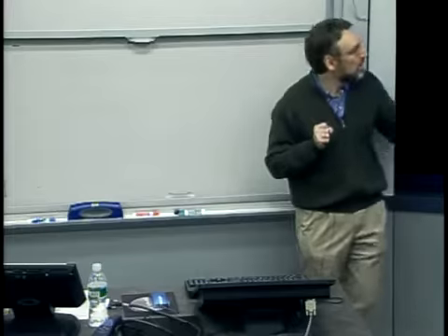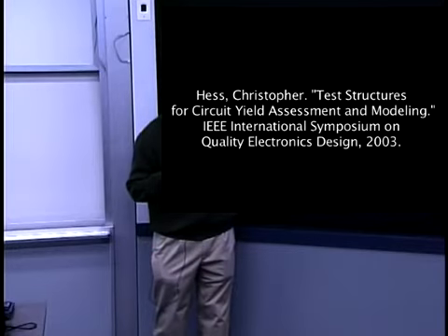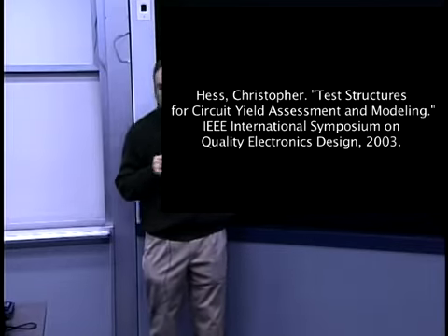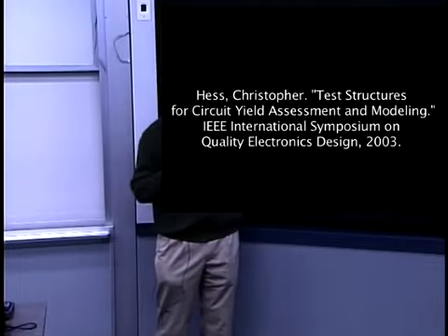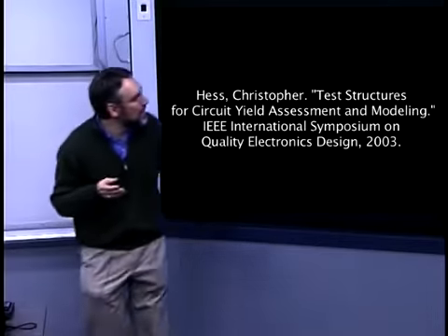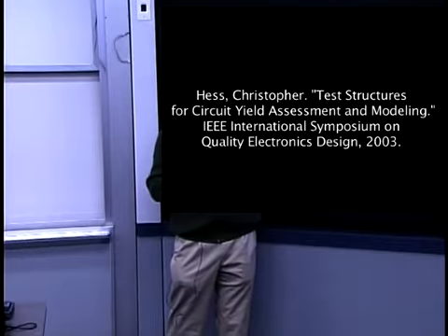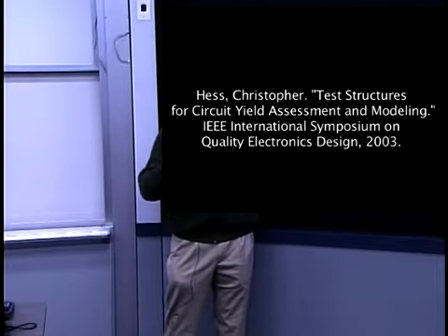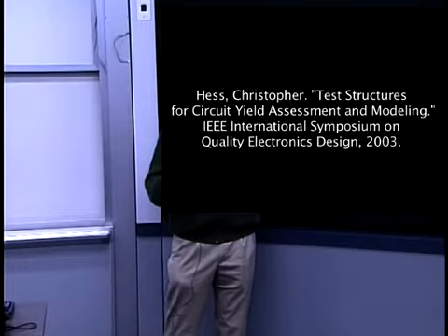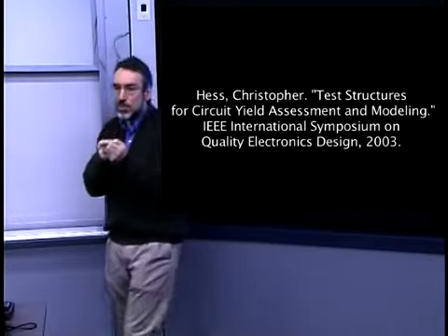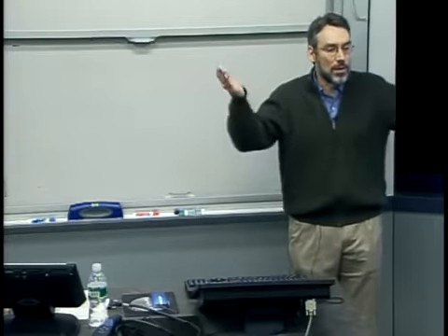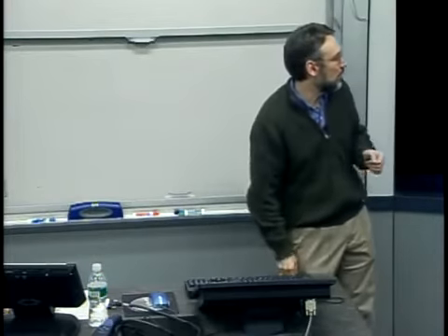What I mean by size is imagine that that little dust particle is only a quarter of the width of any of the minimum feature sizes on your structure. Well, that might mean I lose a quarter of the width of one of those metal lines, but at least it still conducts. It might have a slightly higher resistance than I expect, but functionally I'm still okay. Similarly, if it's too small of a particle to bridge between lines, I'm not going to have a short. So the idea is to control the particles down to a certain feature size.